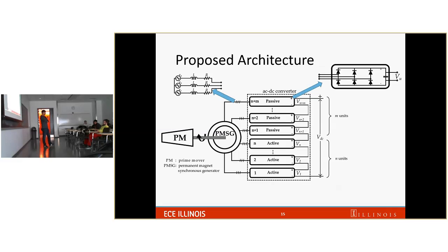Another plus point is it doesn't have switching loss, so efficiency will be improved as well. And the third plus point is it's cheaper. If we look at a diode rated for 1000 amp and 1.5 kV, the cost for one unit is maybe $125, compared to an IGBT of the same rating. The cost for that IGBT is around $350. So we have about 3 times cost saving using a diode bridge.